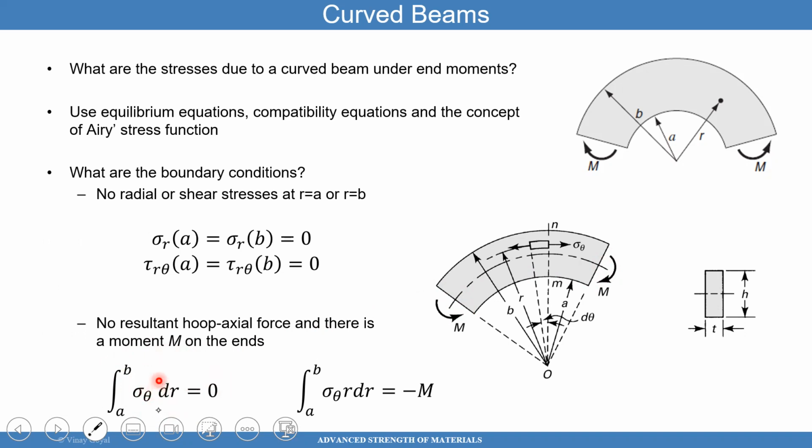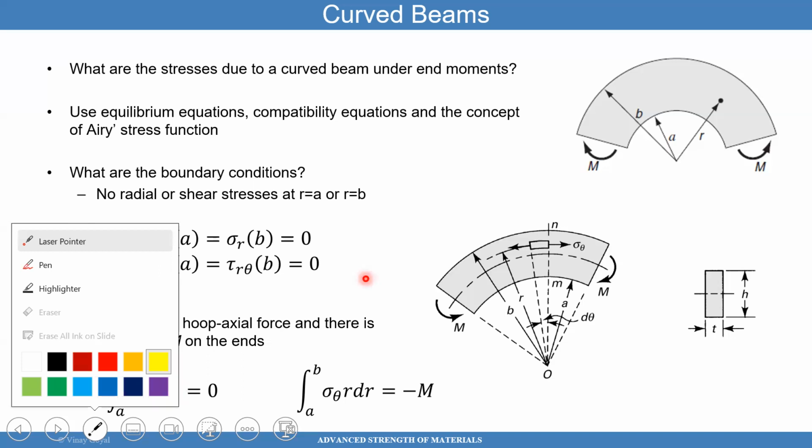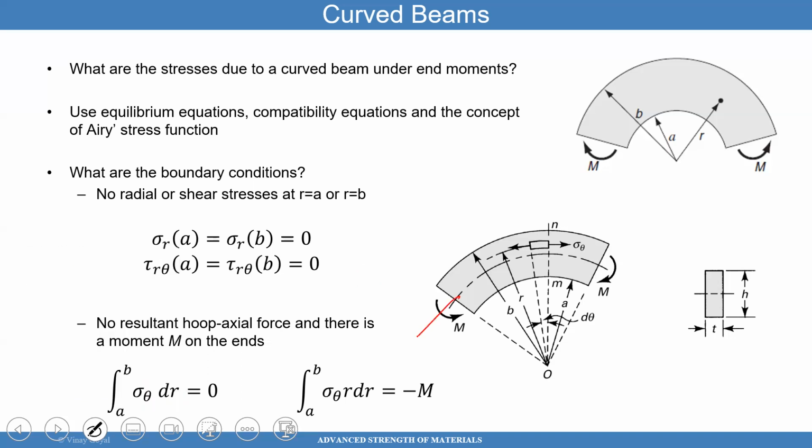In reality, you can put a T here, T is the thickness, and dr is a radial element. When you integrate over that surface, you're getting that whole area there. So in reality, I don't have any axial force applied on this surface. And when I say axial, let me draw it for you so you can see it. I don't have a load applied that way.